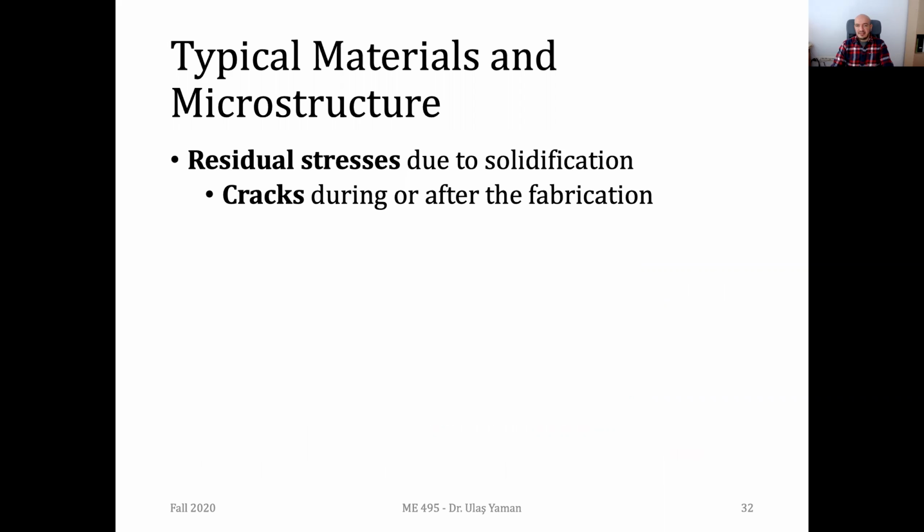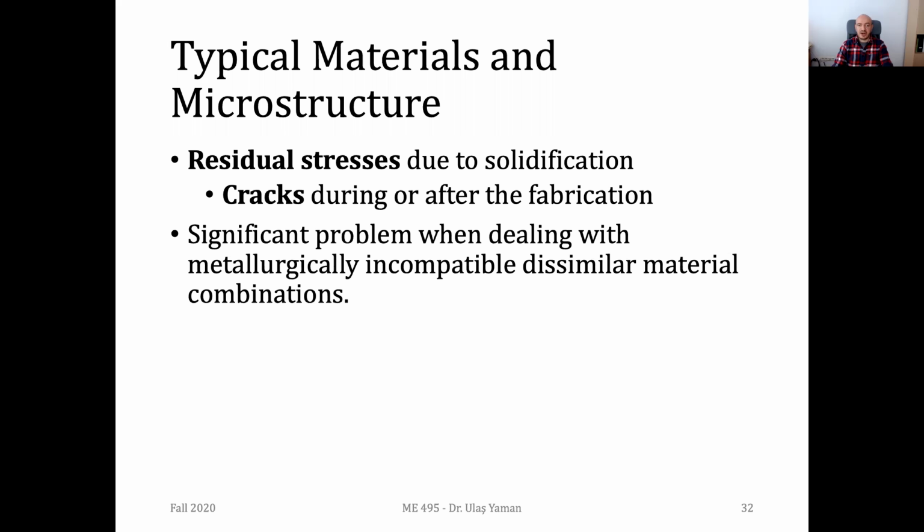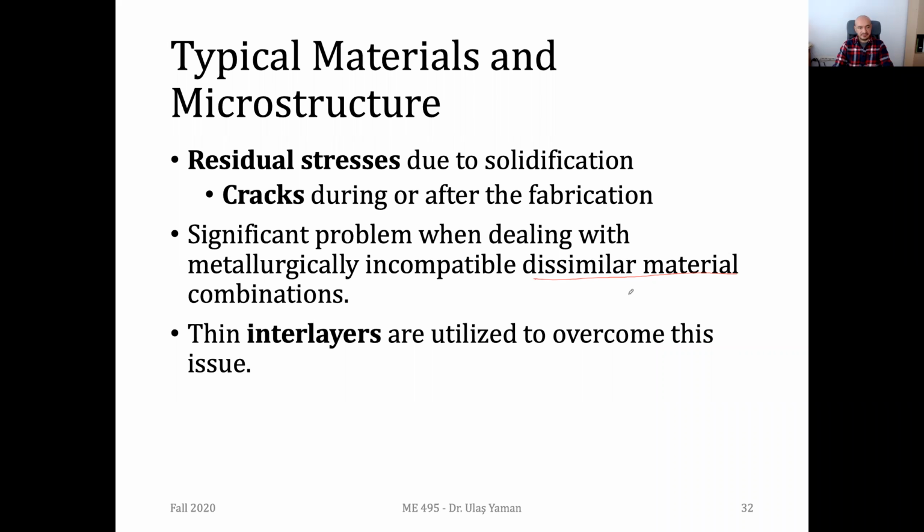So we will have, obviously, during the solidification, some residual stresses actually develop. And once you have them, that means you may have cracks on your part during the fabrication or just after the fabrication. And this might be quite problematic. So you should be adjusting the parameters properly and not have any cracks during the fabrication or after your part is taken out of the machine. And this happens usually once you are dealing with dissimilar materials. So you need to have some experience in terms of material and try not to have such cracking problems.